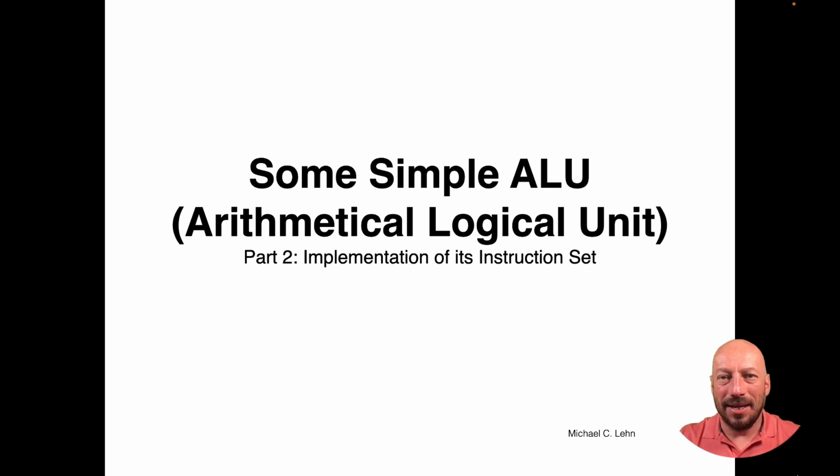Hi. In this video we will finish our little ALU project in Circuitverse. We already have all the relevant components for that. We have this adder with this internal register, this accumulator, and it computes the status flags. We also have these registers, this register bank, and now we have to combine these things. And we also have to define some instruction set and implement it. And I will show you how I did that.